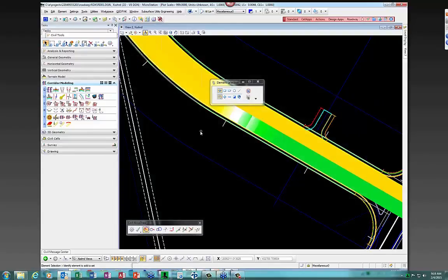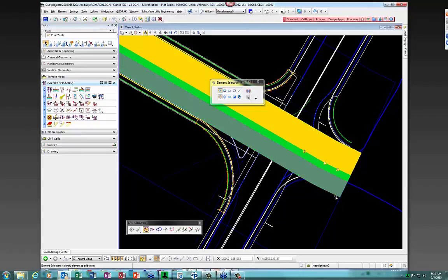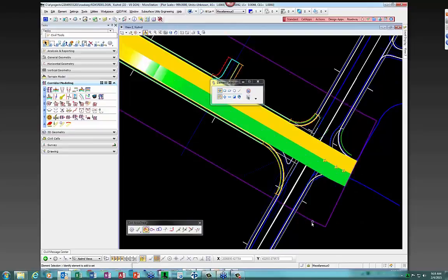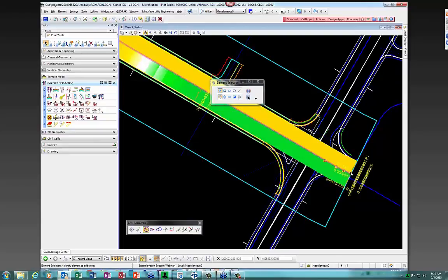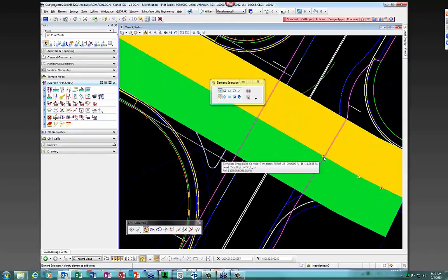and if you need to make modifications now, like let's say, for example, you wanted to change maybe the limits of these sections. So you can click on here, and then if you want to pick these station values, you can graphically change it if you click on this boundary, and then there's a little handle right here. So there's 2 different types of edits. There's the whole section edit, and then there's individual lane edits. Okay. In this regard, these little information shields here are for my design standards on my center line. So that doesn't have anything to do with the super right now.